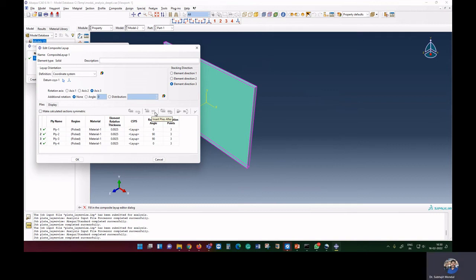One more thing you just see: once we use a single layer solid element, in that case our frequency was coming to nearly 150. And once we compare the results of the composite model using one layer 3D solid element and the whole layer of 3D solid element, we can see both results are very close.